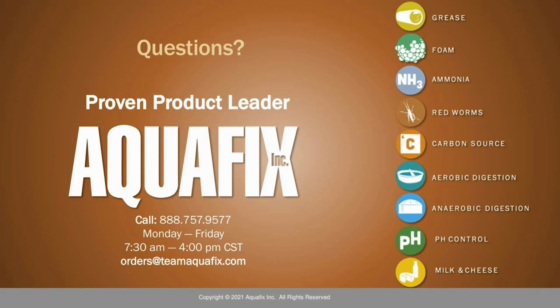But as far as increasing alkalinity, I recommend routine supplementing if you know your digester has problems which would cause it to deplete its alkalinity and generate a lot of volatile acids. So maybe routinely feeding something like our Boost and Lock in low doses to make sure you have an established population of alkalinity to neutralize some of the incoming fluctuations in loading to prevent too much volatile acid accumulation.